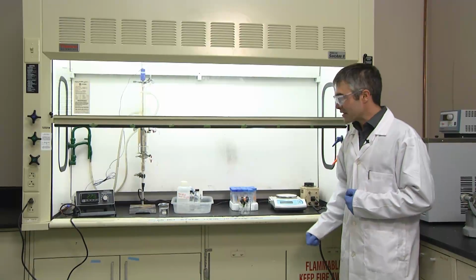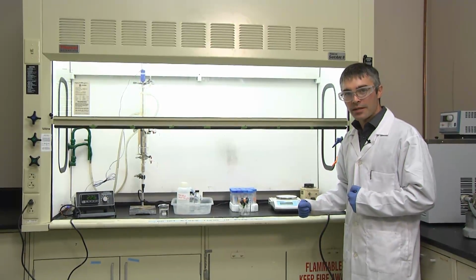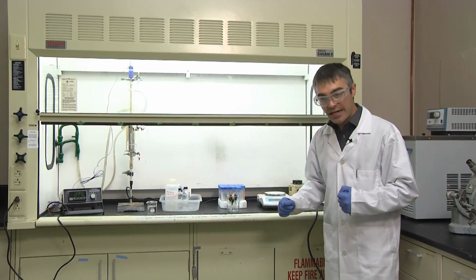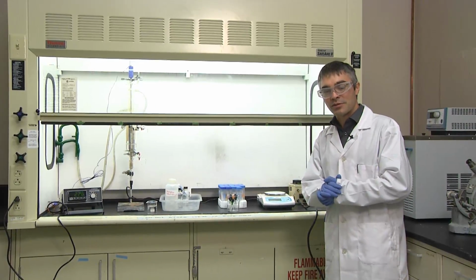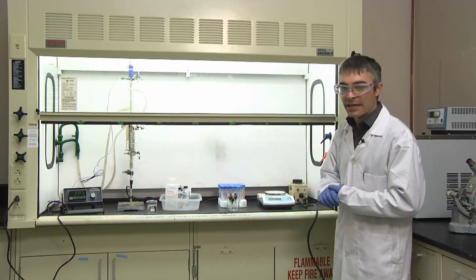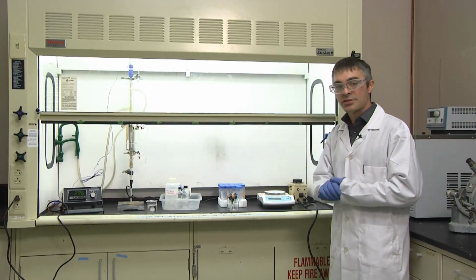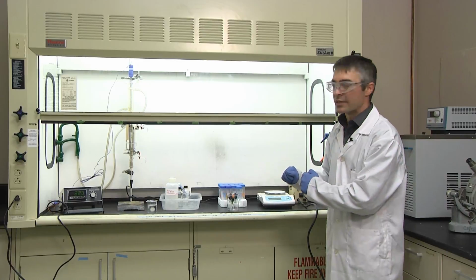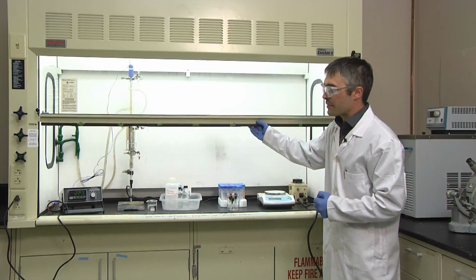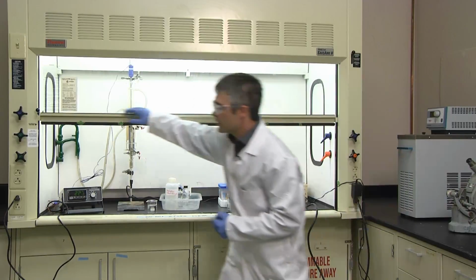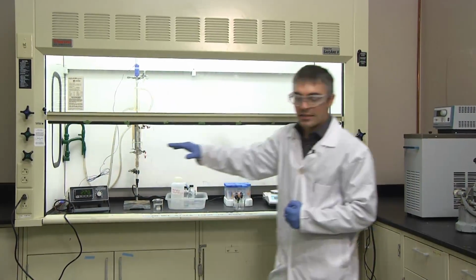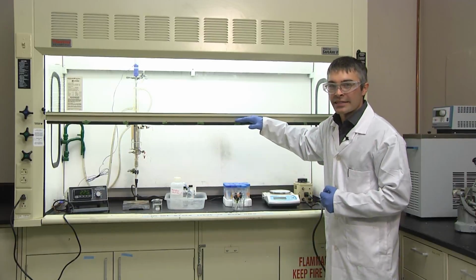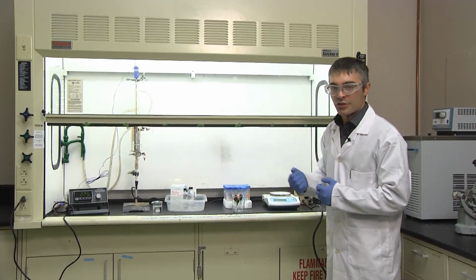All right, here we are at the vapor-liquid equilibrium setup. Before we begin, we want to go over the safety considerations for this laboratory. As was mentioned in the theory section, we will be working with isopropanol and the vapor thereof, and there is the potential for sparks. Therefore, we will be conducting the entire experiment within the fume hood. Throughout the duration of the experiment, the fume hood must be lowered to the set operating height, with the one exception when we'll be loading the apparatus, which we'll discuss when we actually go to do so.